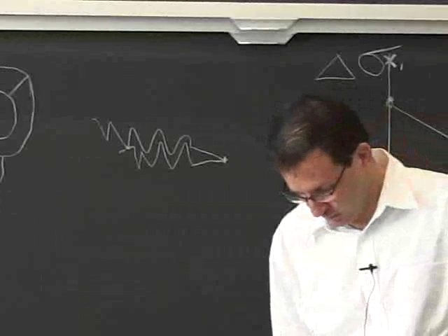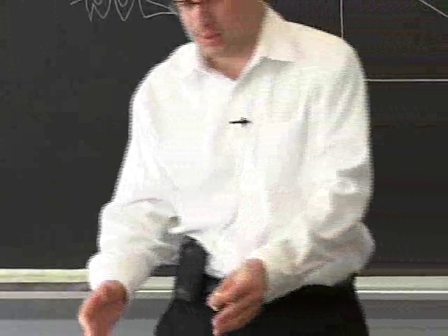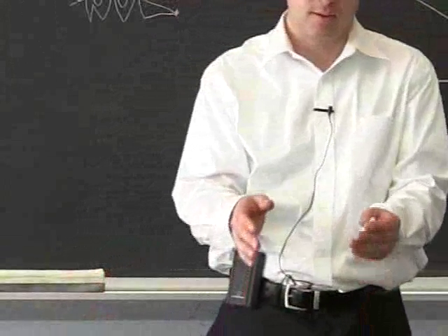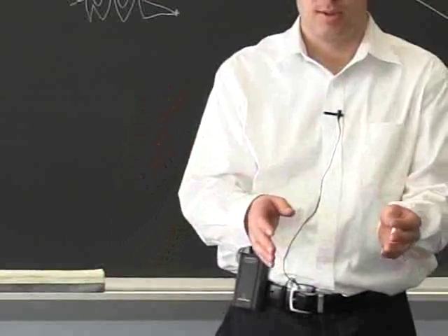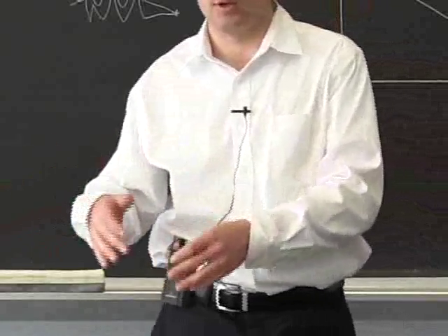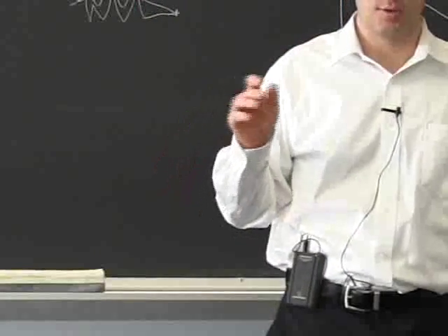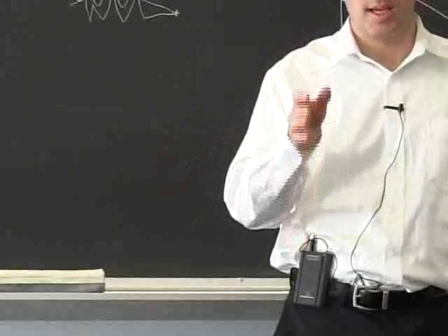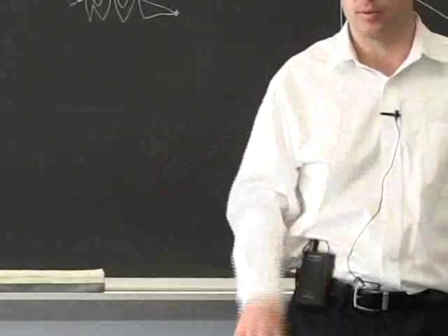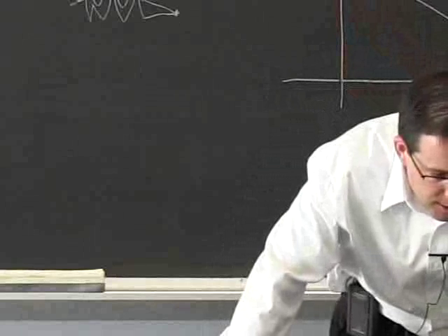I'd say that you don't start from scratch very often. So we ended up making a one-by-one comparison for a specific titanium alloy between a casting and a wrought product that became very specific on all the details, as opposed to brainstorming about all the materials we could use. So we did a little brainstorming first, and then we were close enough to say we'd like to move to a casting, but can we do it? And then we had to go through all these processes. They did. It was a great cost saving.